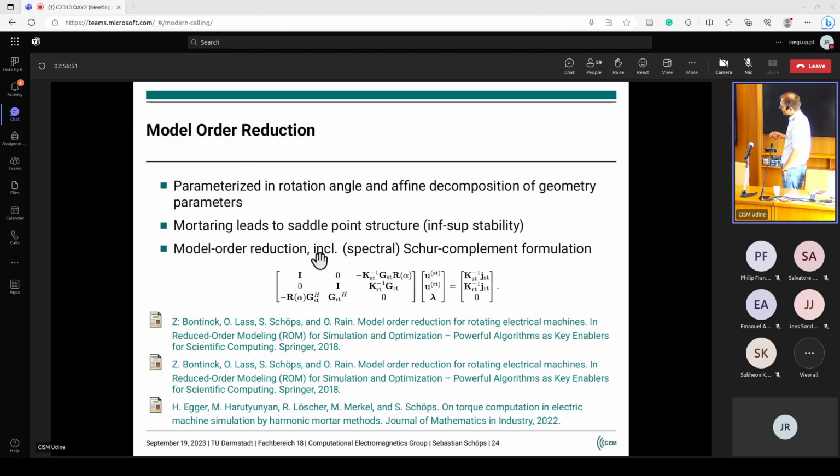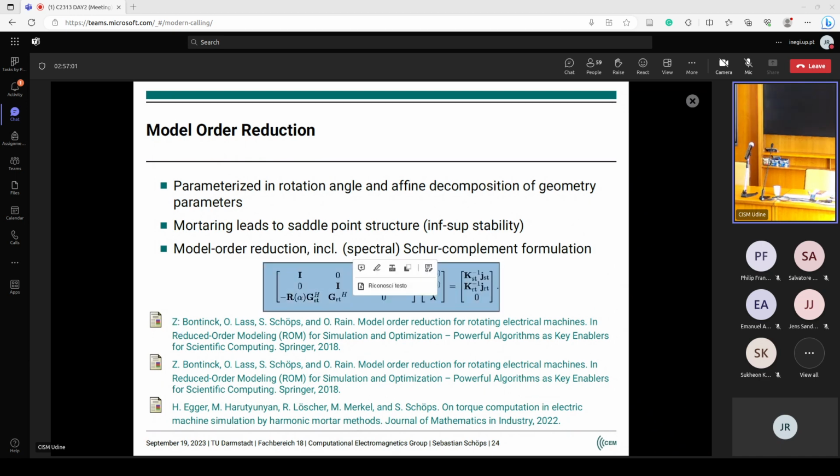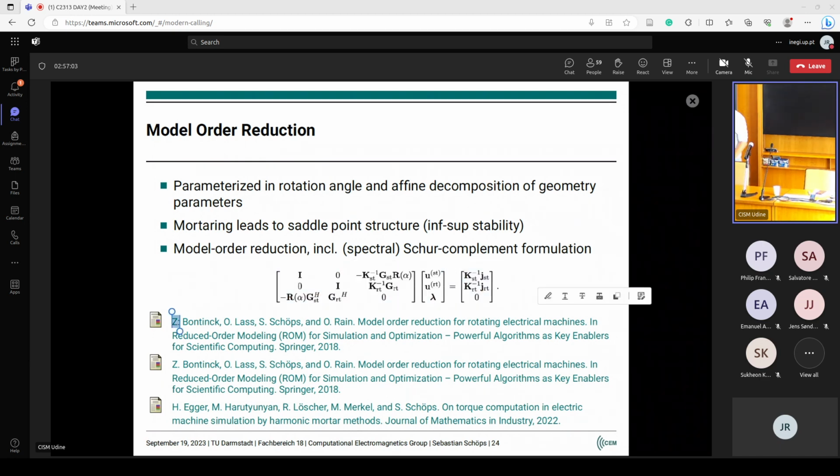What you see here is a specific form of the saddle point problem. I mean, you see there's a stiffness matrix, let's call it like that, and that's another stiffness matrix. Anyway, so, and I will use the pointer. So those matrices originally would have been here on the diagonal, yes? And these would be then the coupling terms there and over there. But what I did here is I formally inverted those stiffness matrices. This led to a very interesting method.